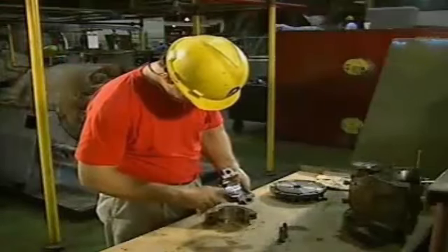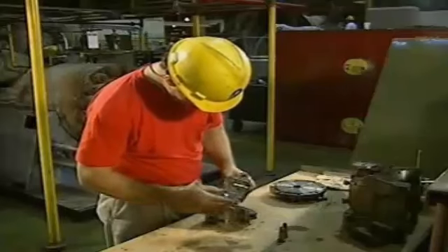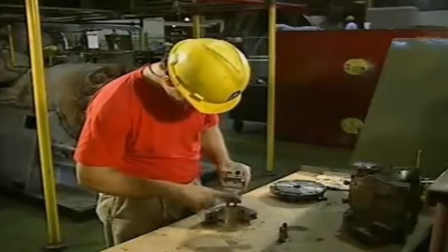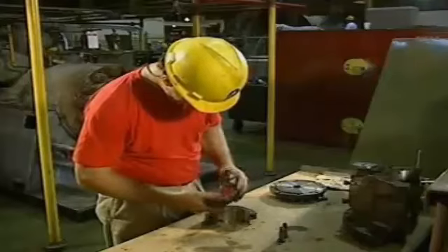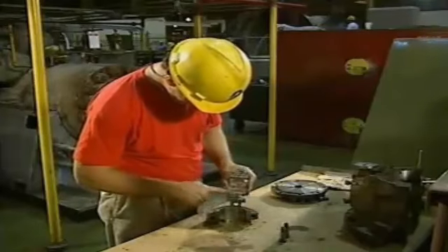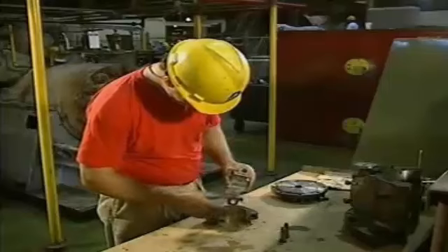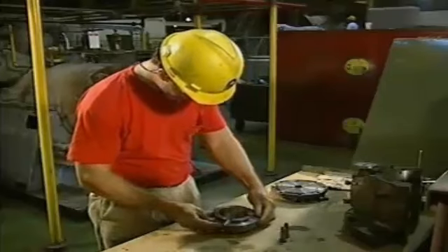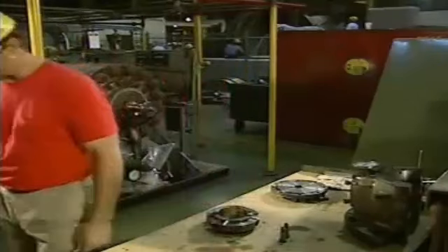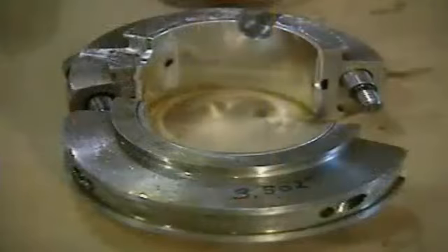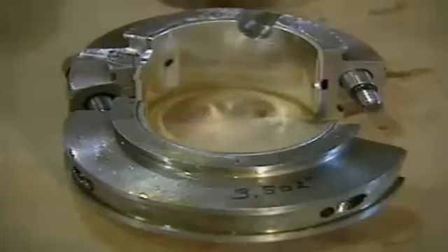The bearing inserts are a matched set. This means that if one insert has to be replaced, then both are replaced. After the bearing has been thoroughly inspected and any necessary maintenance has been performed, the bearing can be reinstalled. When this is done, it's important to make sure that the bearing is properly fitted to the shaft. One way to do this is to check the clearance between the bearing and the shaft.